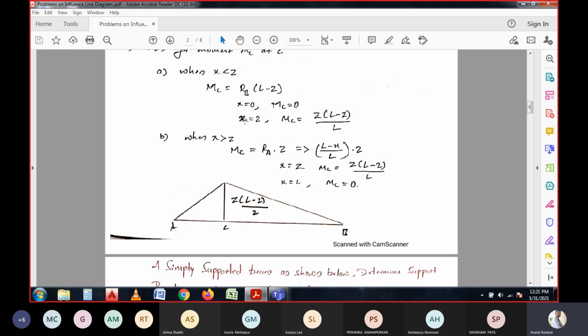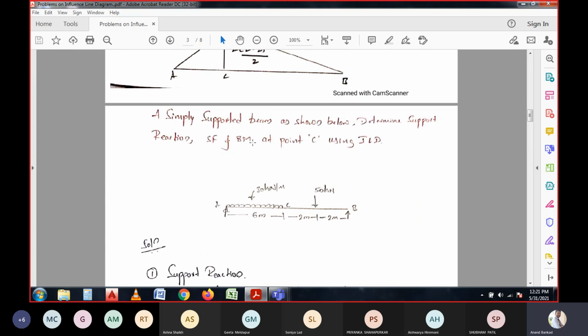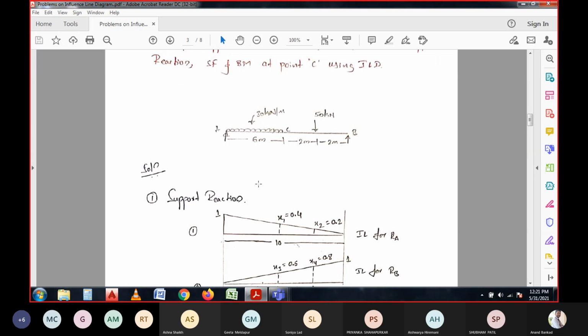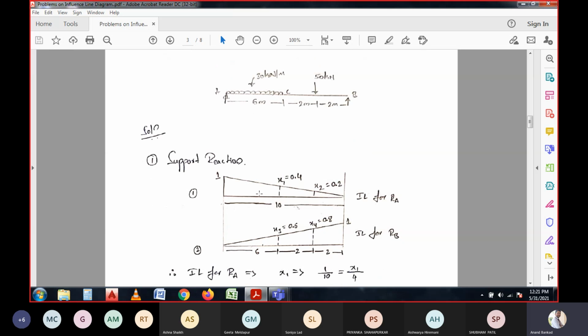And this is what we discussed briefly for a static load on the beam. Also we have discussed this problem. In this problem we have two loads: one is uniformly distributed over the 6-meter span of the total beam, and another is a concentrated load of 50 kilonewton. This UDL is to be considered under the influence line diagram. I will just explain the diagrams over here, and then we can discuss a new problem in this class.